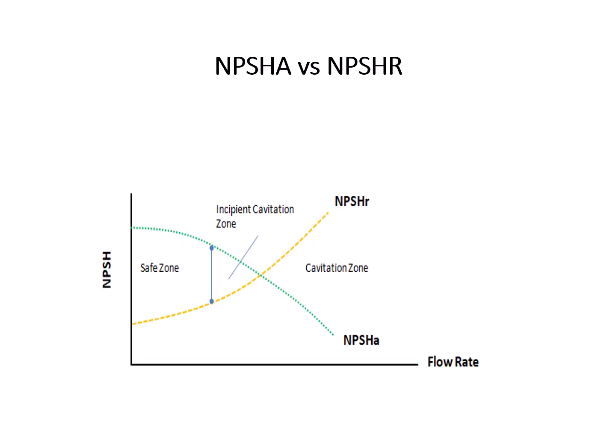And this curve is very, very important. It shows you the net positive suction head in general compared to the flow rate. The yellow one is the required pressure, required by the manufacturer, by the pump to work, and the green one is the available, as per your system design.